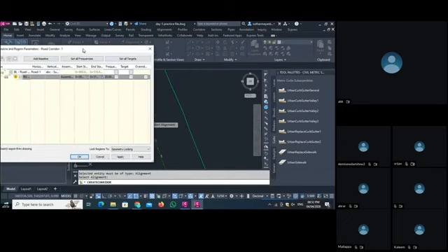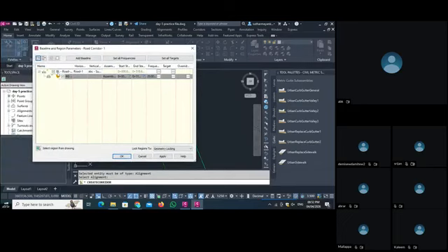As you select the OK button, you see two things. BL is the baseline and RG is the region. So the corridor is created with the help of these two things, baseline and region. In this region, you can see all the things: the horizontal baseline, this is our vertical baseline, these are our assemblies, this is our starting station and end station.